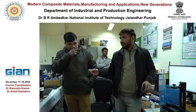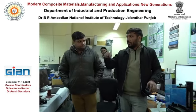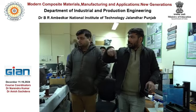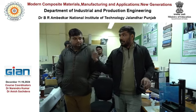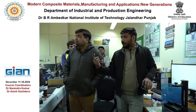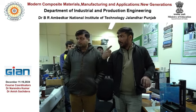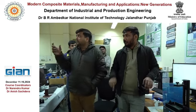In the SLA process, if you know the SLA process, it is a kind of laser process. Means the laser will fall and the curing will take place along the track. But in DLP, the whole layer gets cured at a single time. Like UV light is projected on a surface area, and the whole area gets cured. At a time, a single layer is formed.